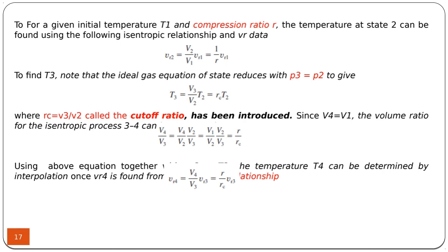In isentropic compression and expansion, you can use the air table. This is for compression, and also the same thing can be used for expansion because it's also isentropic. During the combustion, because pressures are the same, you can calculate the temperature.